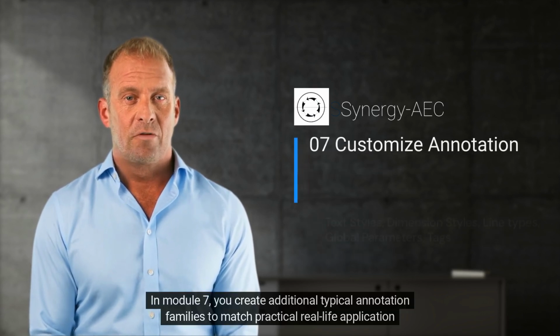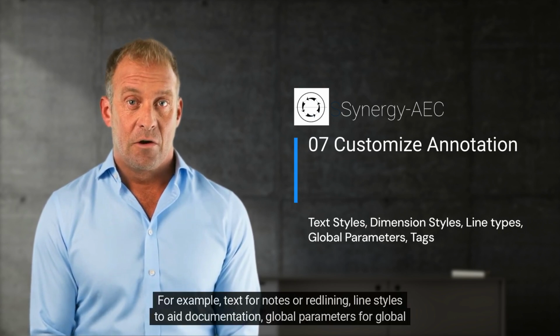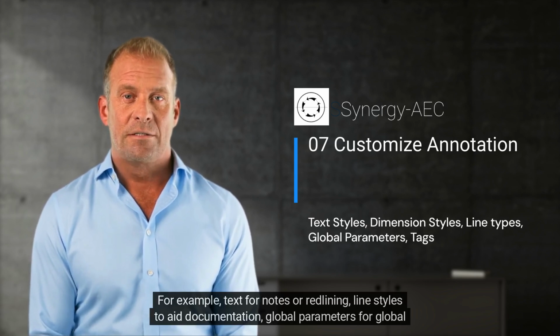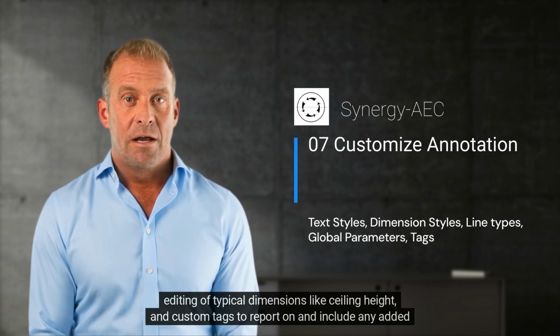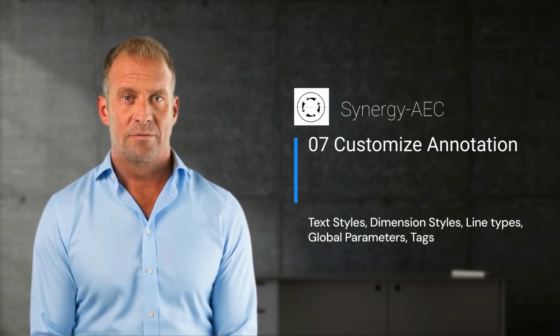In Module 7, you create additional typical annotation families to match practical real-life application of these features. For example, text for notes or redlining, line styles to aid documentation, global parameters for global editing of typical dimensions like ceiling height, and custom tags to report on and include any added parameters.